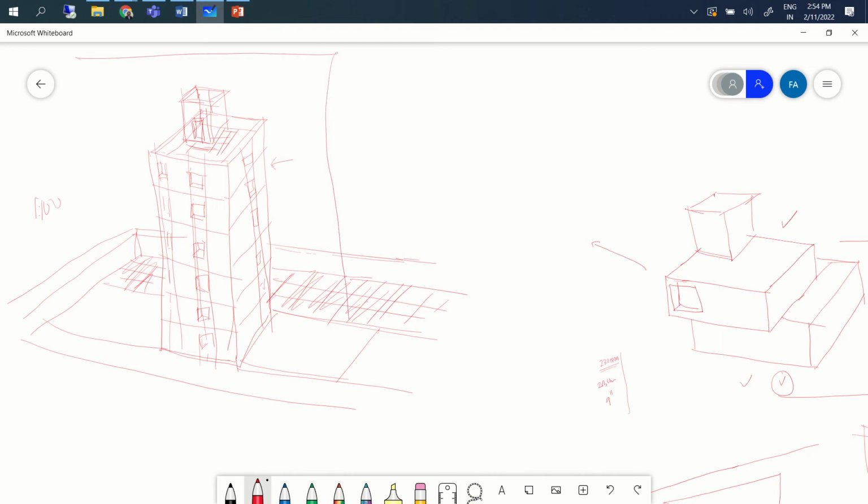Okay, let's say this is your drawing sheet. Probably you do this in the portrait format. That will be better. In horizontal format, what will happen is you are already restricted by height, right? You are leaving some space for writing and you are left only with this space. Let us say this is going to be 30 centimeters. 5 centimeters you are doing for writing and another 1-2 centimeters for the margin. So how much? 7 centimeters has gone. It's only 21 centimeters.